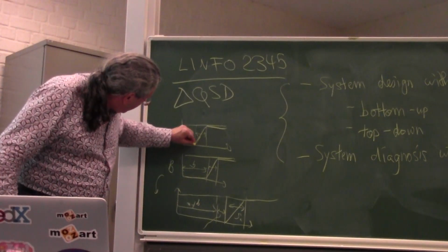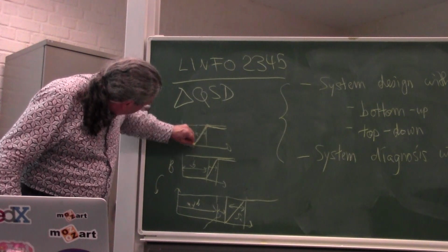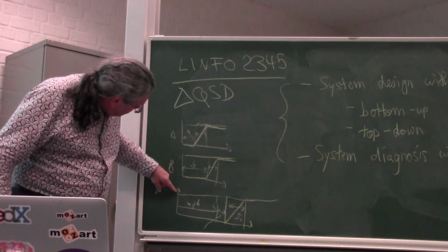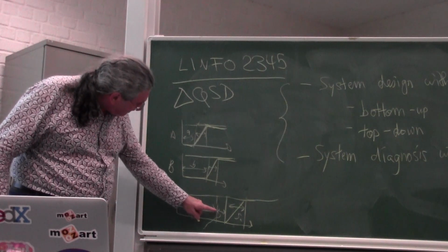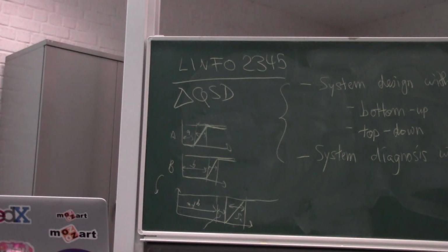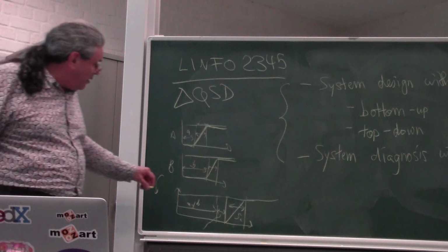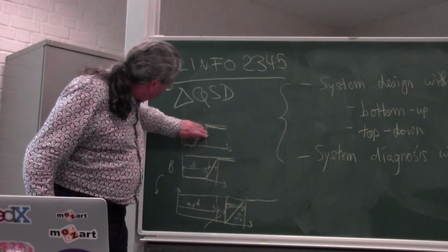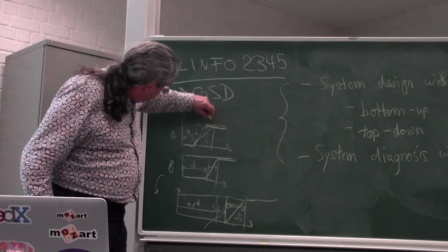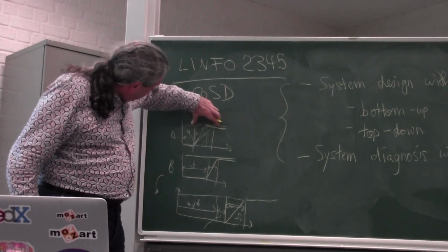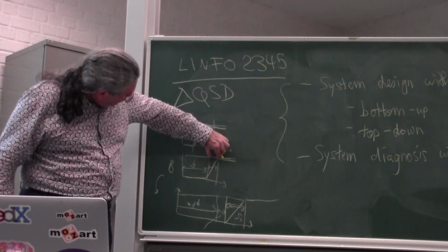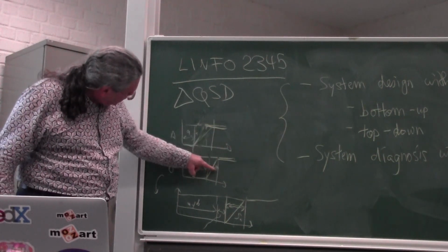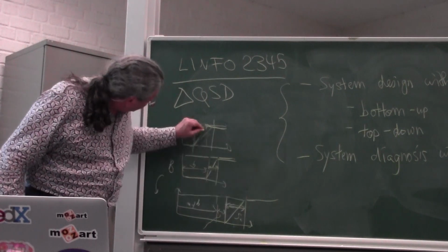Because these guys are actually varying between these two values, the minimum delay, if you do the computation, is actually a little bit more than A plus B. It's A plus B plus M. And M, if you make the computation, is the minimum of those two spreads divided by 2. And the spread here, this spread, is actually the maximum of the spreads. It's not the sum, it's the maximum. So if one of these guys has a big variation, the other one has small variation, then this guy will have almost no effect, and the output you will see the big variation, okay?